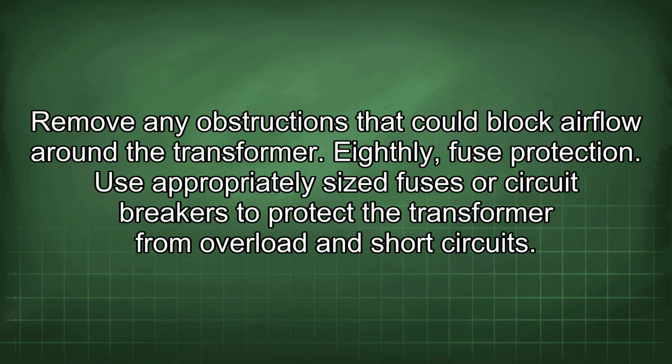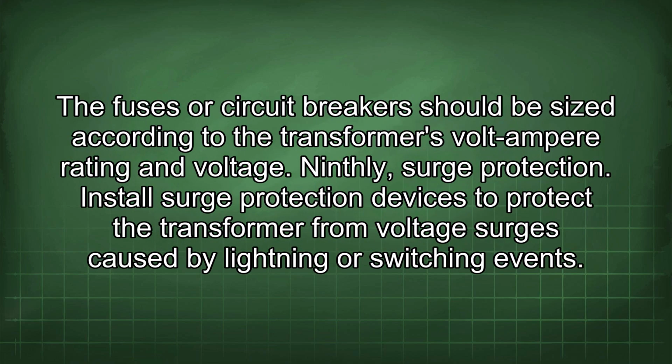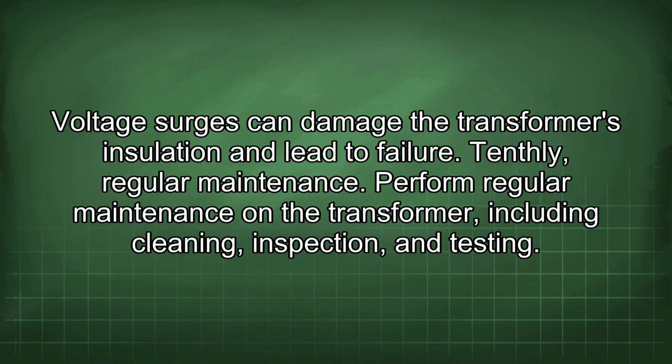Eighthly, fuse protection. Use appropriately sized fuses or circuit breakers to protect the transformer from overload and short circuits. The fuses or circuit breakers should be sized according to the transformer's volt-ampere rating and voltage. Ninthly, surge protection. Install surge protection devices to protect the transformer from voltage surges caused by lightning or switching events. Voltage surges can damage the transformer's insulation and lead to failure.